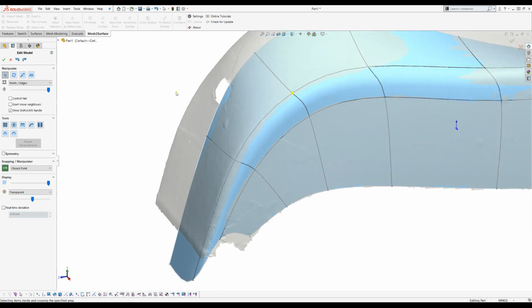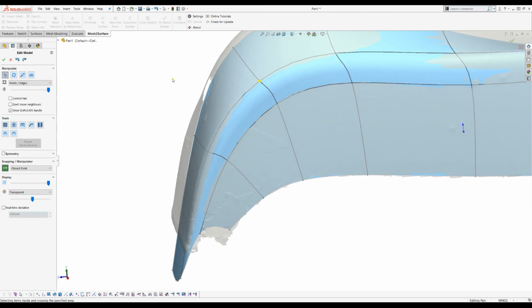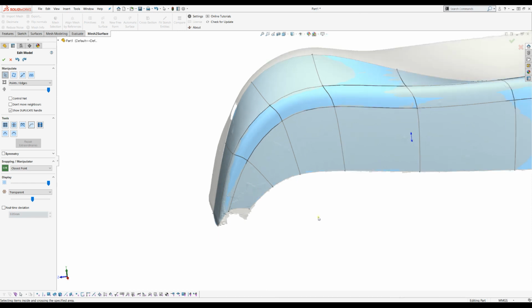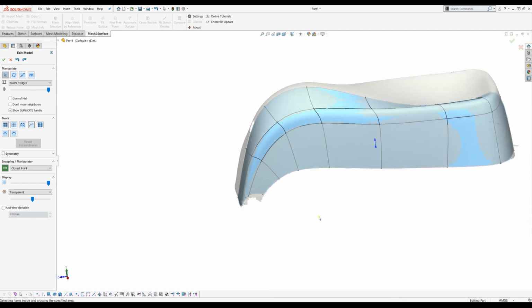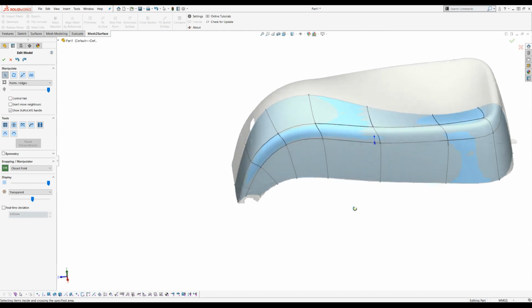If I just turn this snapping on, I may want to get everything projected back to the mesh. In this case, there is a command called snap to mesh. If I press snap to mesh, it will take the selected element and project it on the mesh. That's why you saw that this didn't go on the mesh. But if there is nothing selected, if I press snap to mesh, all the points will be projected to the mesh. So this is powerful, but at the same time dangerous if you don't have a selection to project everything, if you have some noise. So use this carefully.